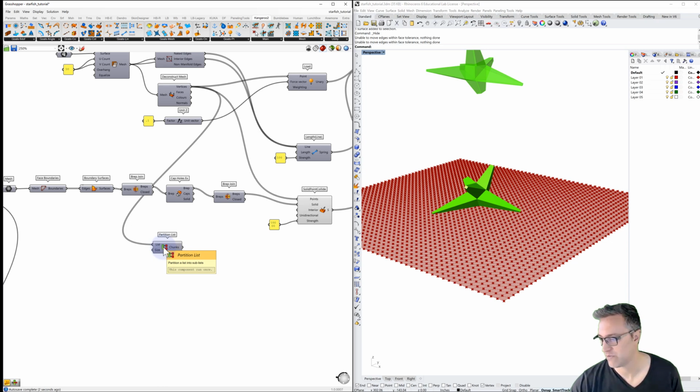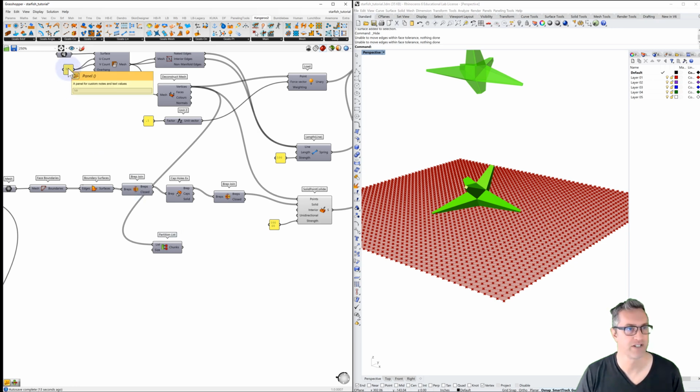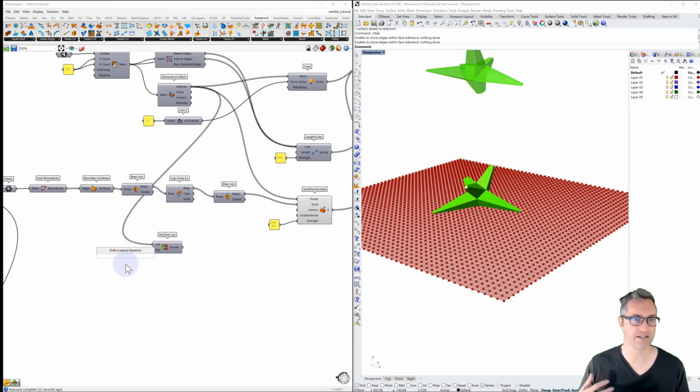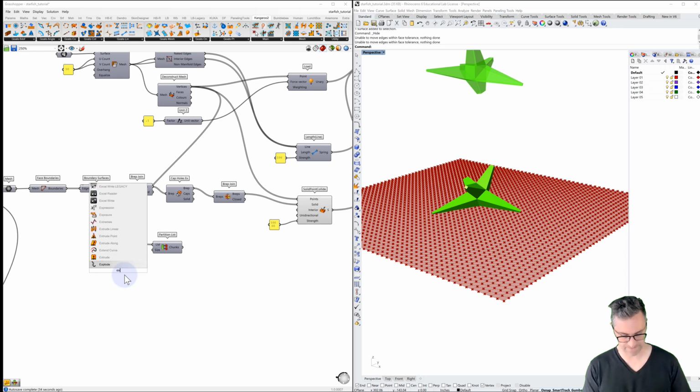And what we basically want to do is add 1 to the size from our value up here on the top. So let's do that with an expression. I prefer to do this using an expression. Again, like I said, sometimes we come back to our Grasshopper files, and if it's been a while, you may not remember. We can always add a +1, but it's embedded within there. So I much prefer to use an expression.